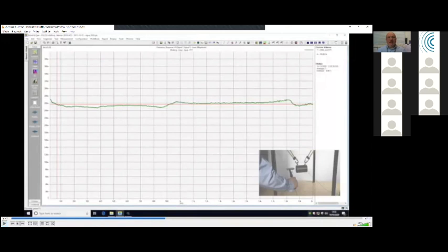Okay, so here's the analyzer screen now. So we have accelerance here, and we have the quantity that's being measured. And you can see as we hit the block, may not be exactly in time, you can see the number of averages here increase.